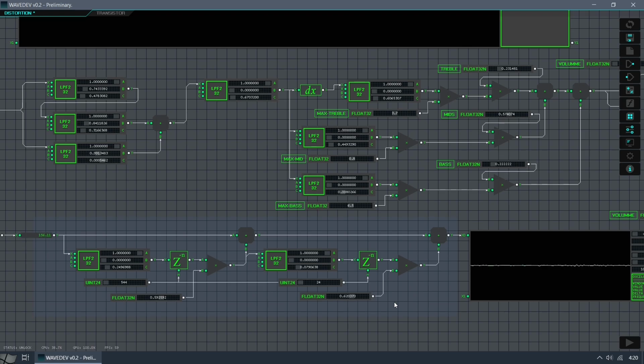Simulating a room's acoustics can be much more complex than what I'm presenting here, but it will serve to illustrate the concept quite well. I'm going to simulate a couple of reflections produced by the walls of the room. As we learned from the previous tutorial, we use circular buffers to simulate these reflections. A low-pass filter will be added to each reflection to simulate some high-frequency absorption. With this, our distortion will sound less dry.